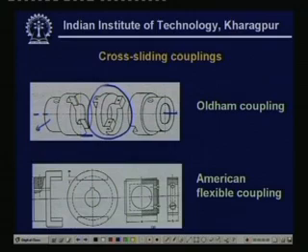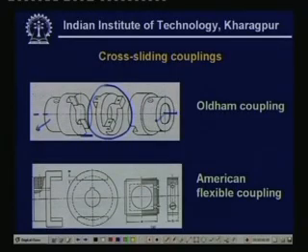How does it add to flexibility? You see, whenever there is a little offset from this distance, now here one point is that Oldham couplings work when there is a parallel offset. It does not take much care of the angular misalignment, but whenever a parallel offset is there, this coupling, that is this part, gets engaged, but it can slide over this slot. So the length of engagement in the slot gets changed, but it transfers torque from one shaft to the other shaft.